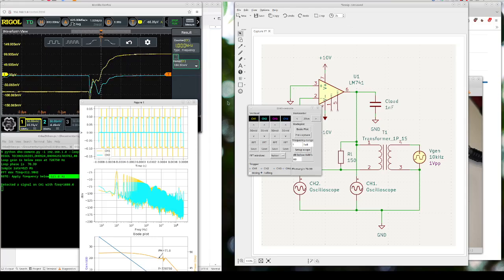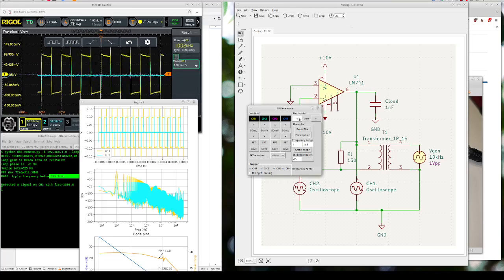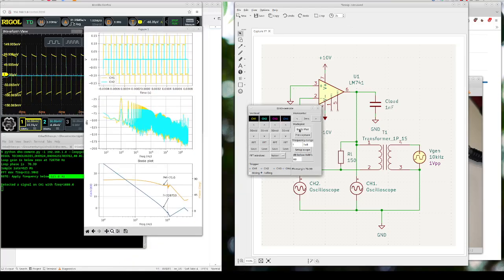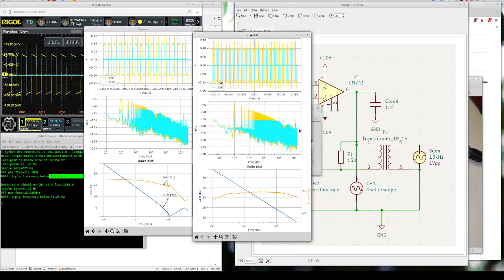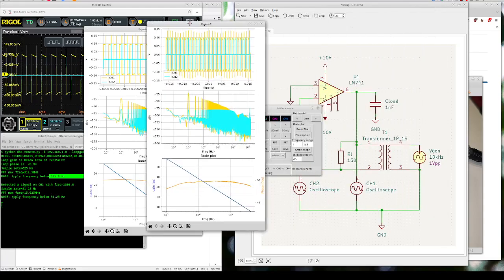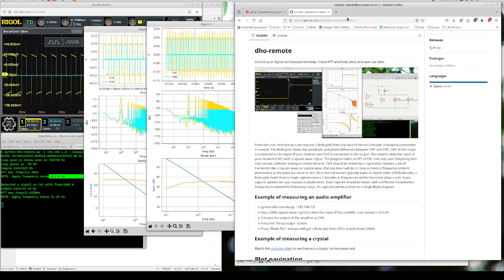But for now I'll just ignore that a bit and just show a number of cycles and give the Bode plot. It is about experimentation. Just see how the Bode plot looks like and if this is what you want to have. So now you see that it starts from 1 kilohertz and the gain has increased all the way to 60 dB.